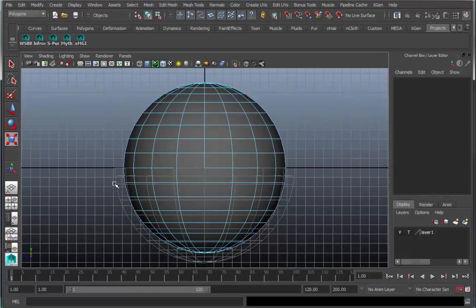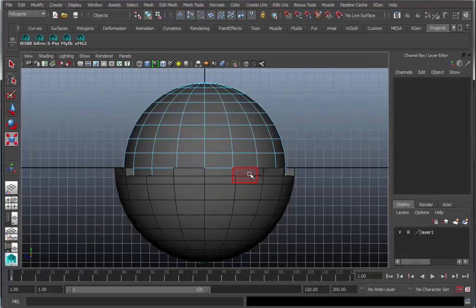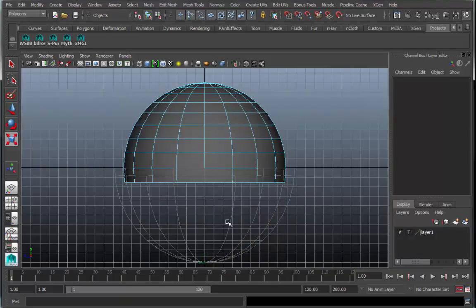So if I came in here and just said, yeah, okay, I'll delete all these faces, well, wait a minute, you're actually going to have some gaps now, because you can see that the rampart top of the bottom has this sort of toothy gear edge that goes up and down. So you actually want these polygons in the top sphere to stay untouched. In fact, let's just make sure that we do not touch that entire ring. So we want to grab this ring instead. That's the one you want to press delete on.